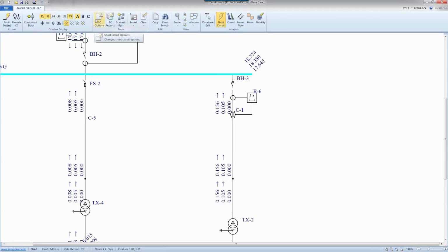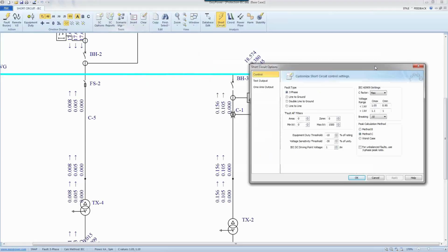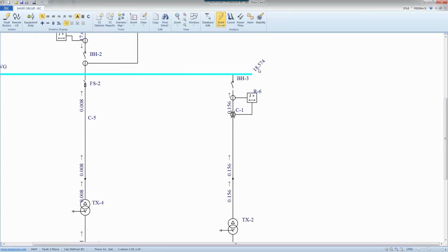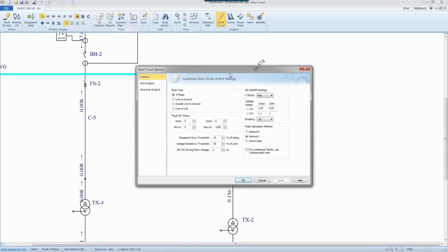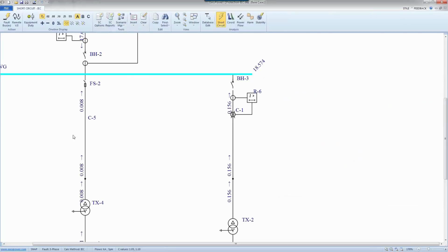Let me just go back quickly and talk a little bit about Cmax and Cmin. So this is Cmax, and if I go and change this value, let me just do that only for initial so that we can focus on one number. So 18. So Cmax, as I said, is a mechanism, leverage, point, parameter IEC defines and allows the user to play with, so that it can come up with a range of the worst case scenario or the highest fault value versus Cmin for lowest fault value. And you can see that here. Right, that's just an impact. I'm just trying to give you the leverage and then also clarify how this IEC terminology translates from IEC code to EasyPower values.